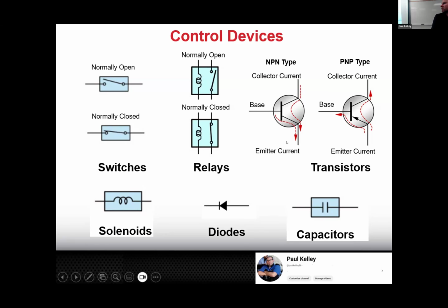And then I can use my meter to measure right here, which is outside the ECM, and be like, is this transistor providing power for the fuel pump or not? Kind of make sense? And if I command it to provide power and I go over here and it's still not providing power, I could reasonably say like, hey, this has a bad transistor. At that point, what do you think I would do if it's got a bad transistor? I told you this once. We don't replace transistors. You're going to be like, oh, it's got a bad transistor, which means it's got a bad ECU, which means price the ECU, get an estimate on it.